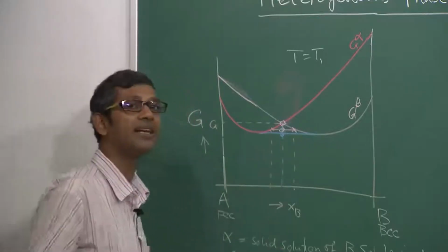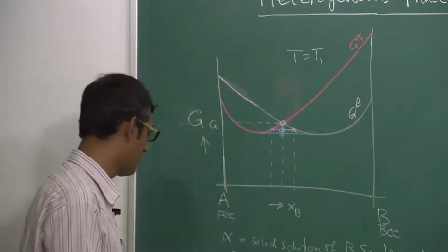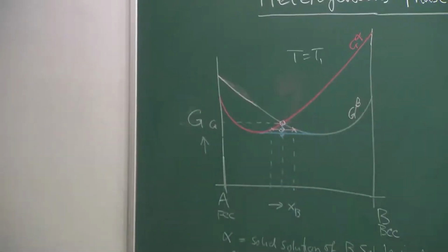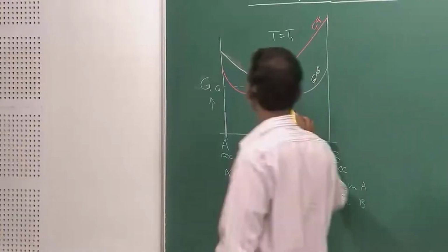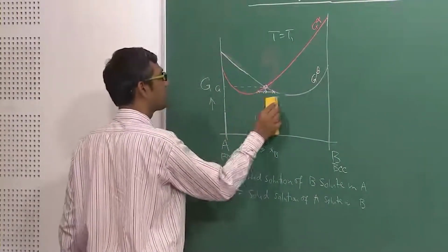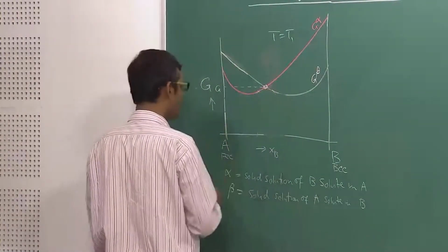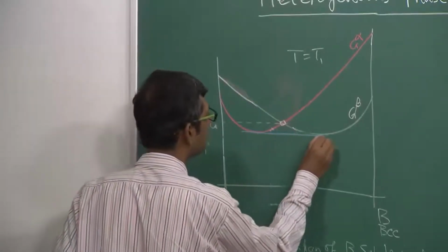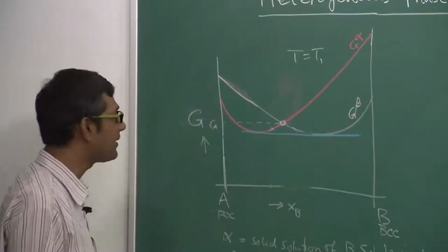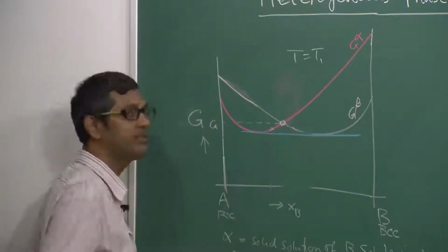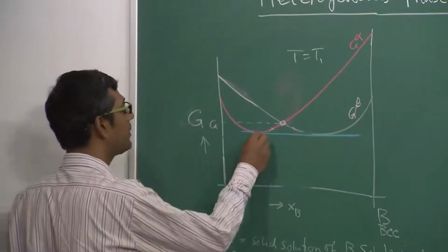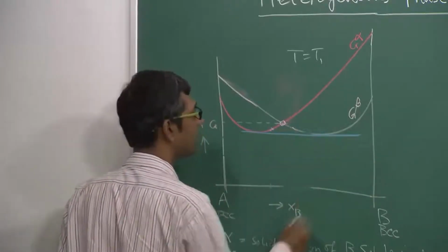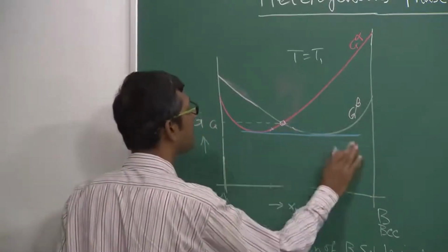So now the question is how far we can go down. That will be clear once I erase part of this and explain. If I erase these things and draw a nice plot, then it will be clear that if I draw a common tangent between these two, I will be touching the lowest portions of these free energy curves, and therefore it cannot reduce any further, because I cannot draw a straight line like this; it is not going to be mathematically correct.